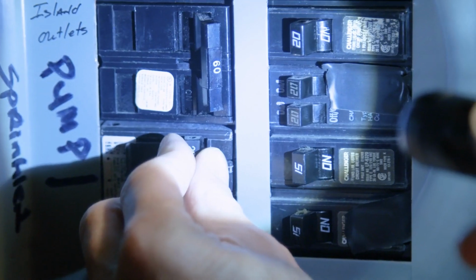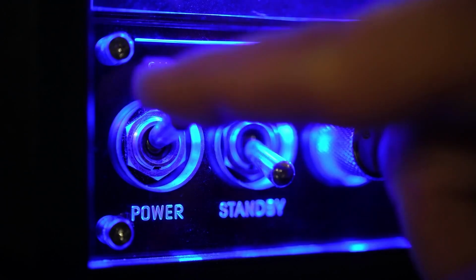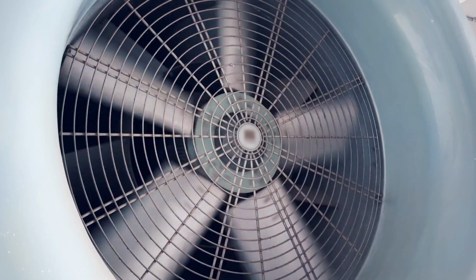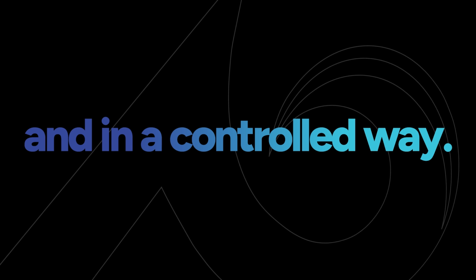And because of this, purging and inerting are not commonly used as they can stir up the dust and just create a bigger risk. If dust does get into an electrical source in a Class 2 area, the machine should be switched off and the dust removed using a high-powered fan carefully and in a controlled way.